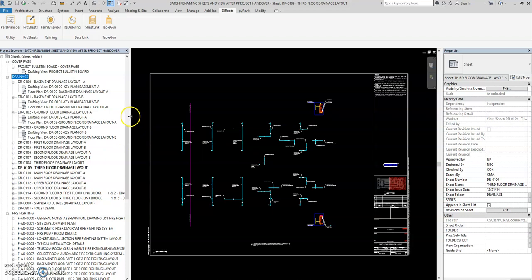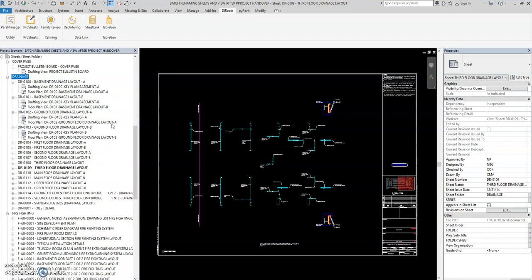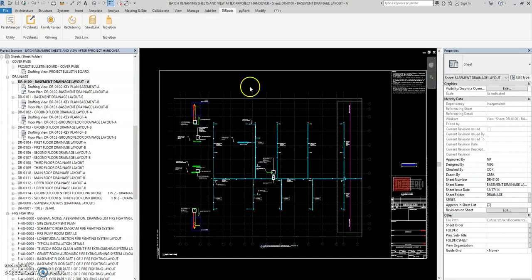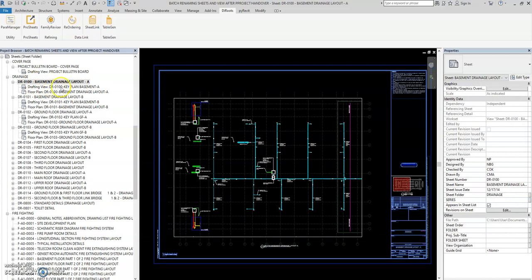If you can see here the views, open this one: all the views inside these sheets have a name and a corresponding project number based on this one. I automate it using the Ideate sheet link, and then I'm using Google Drive to open my Excel and push back to Revit.